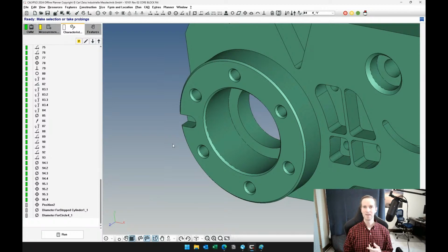So the same would apply for an outside diameter, like a shaft. You'd have two separate diameters, two separate features. You can just put a 3D line through it or create a combined cylinder from both, and that becomes your datum.